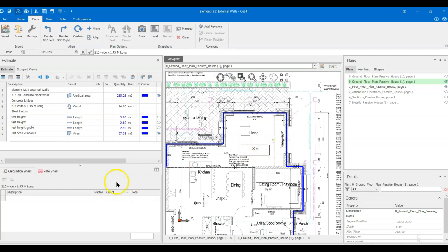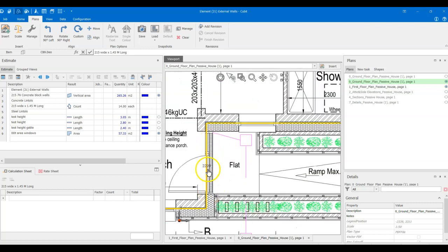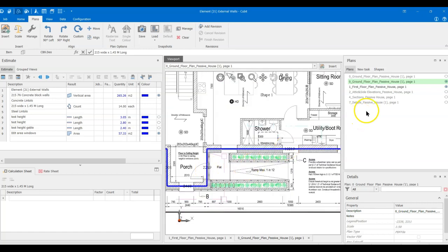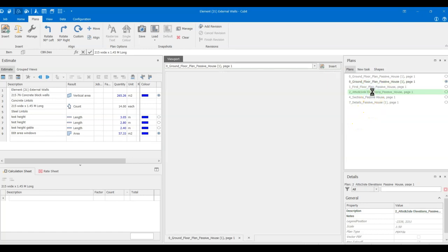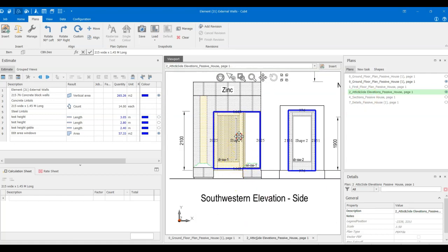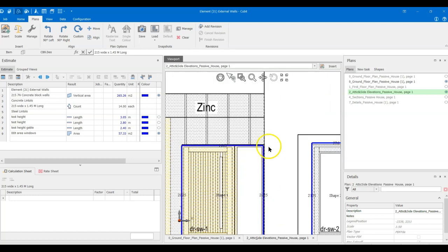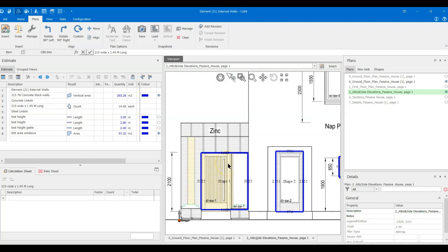So the next one is the side elevation entrance door into the porch. If I go back to my side elevation, in my case, my dimensions are stated on the drawing. You might have to check around with yours. I have 1663 for my width, and I'll allow twice 450, so that will be 2050. So I'm going to say another one there.